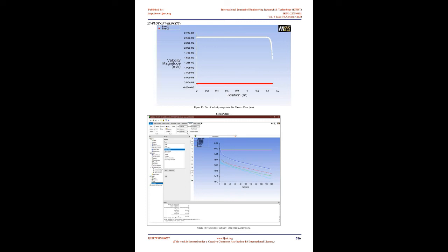For this fine mesh, the edges and regions of high temperature and pressure gradients are finely meshed. 4.2.1. Y-plus values. Y-plus values play a significant role in turbulence modeling for the near wall treatment. Y-plus is a non-dimensional distance. It is frequently used to describe how coarse or fine a mesh is for a particular flow pattern. It determines the proper size of the cells near the domain walls.